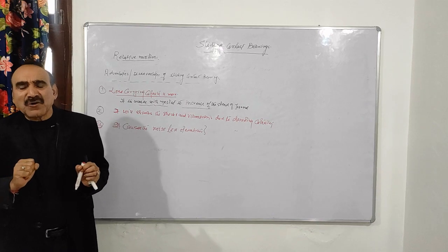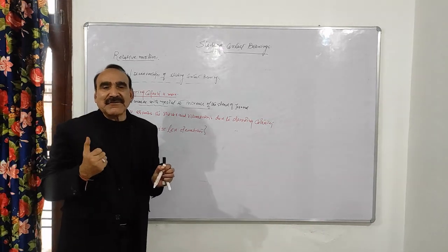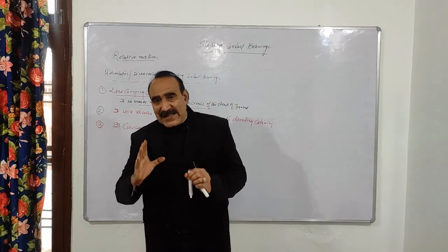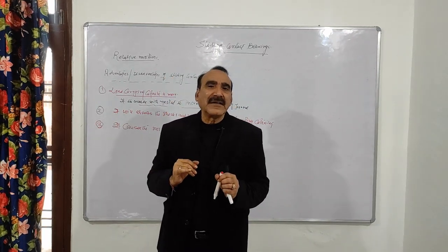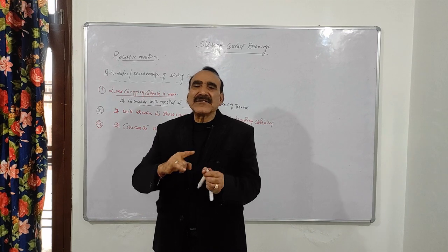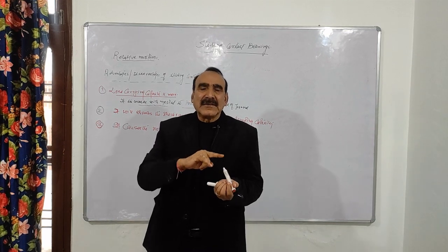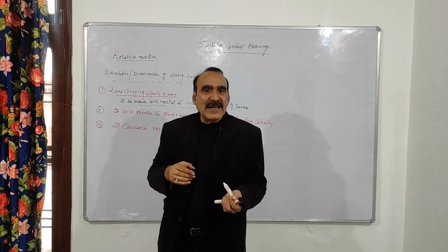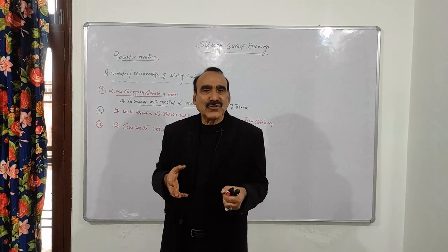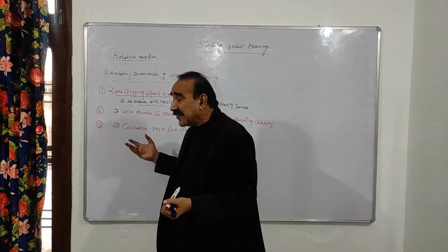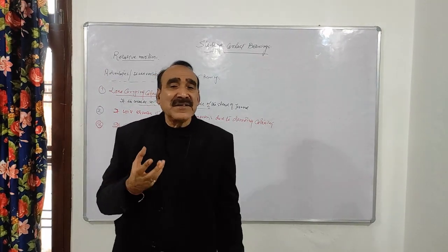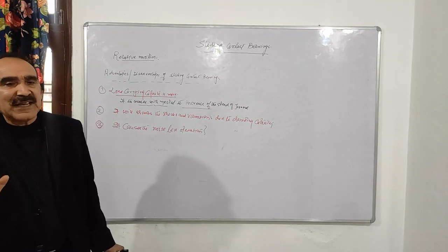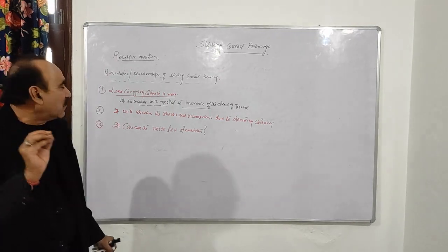One more advantage I will give you. Its service life is not fixed, as in the case of rolling contact bearing, where the service life is fixed, that is 10 to the power 6 revolutions, and also depends upon the speed. Here, the service life is not fixed, right? And moreover it doesn't depend upon the speed.